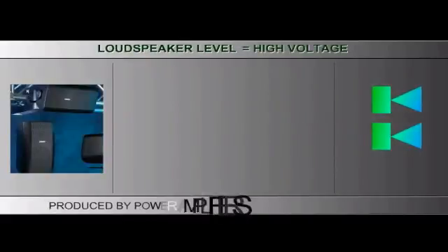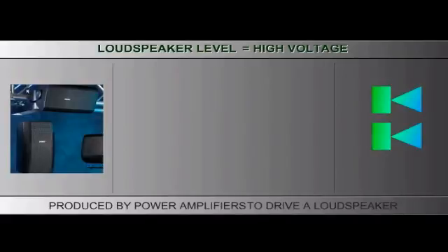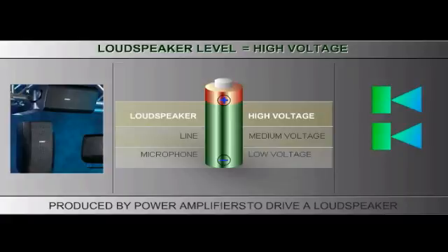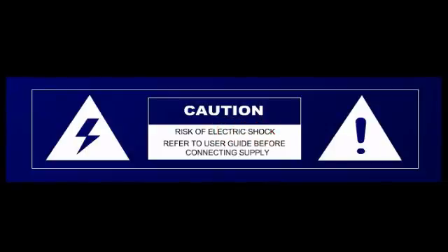Loudspeaker level is a high voltage level produced by power amplifiers to drive a loudspeaker. The voltage range depends on the power amplifier's rated output. It is imperative to match a device's input and output levels correctly.